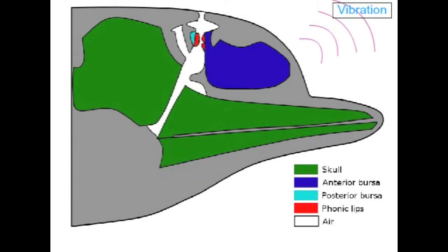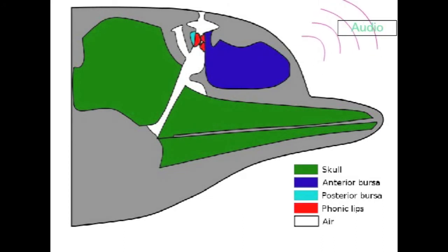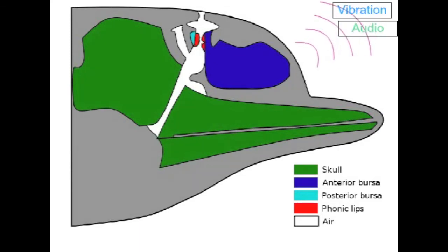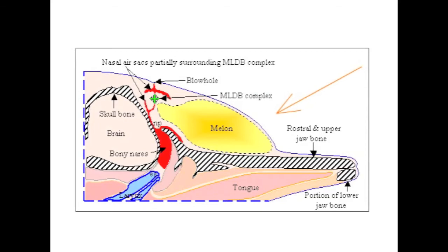The vibration sensor would not be affected by external sounds but has the disadvantage of picking up stray movements. The audio sensor would be good for disregarding the stray movements but will be affected by external sounds. Hence, using a combination of the two would be best. Now, where do we attach it? What are we going to be sensing exactly?